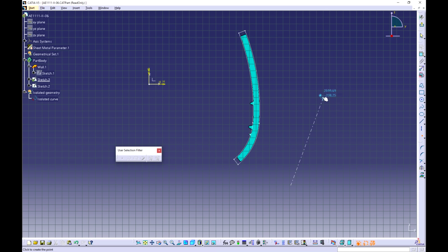As you can see, the indication, the blue circle to the left of my cursor. Click it. Also at the other end of the axis. Click it. And 2 points on the axis, like this. So we have in total 4 points on the axis. Now we are making constraints for it. So first we drag it up a little bit. Select everything from your axis, drag it a little bit up so your first point is over the x-axis.